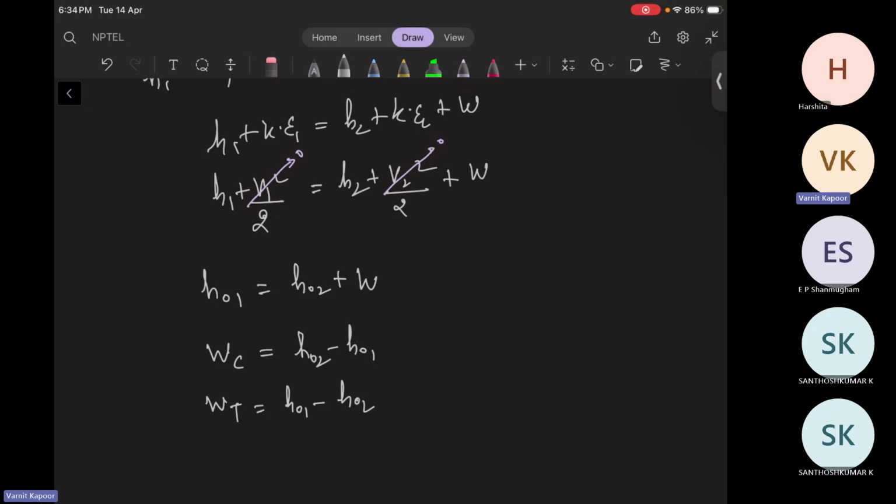So basically what we are doing, we are saying that stagnation state is a state that works as a reference to represent the total energy of the fluid at that particular point. What I mean is that the total energy at the inlet was H1 plus V1 square by 2, but we made V1 to be 0. What we mean by that is that we already added the V1 energy in the enthalpy itself, and brought our fluid to the rest condition.